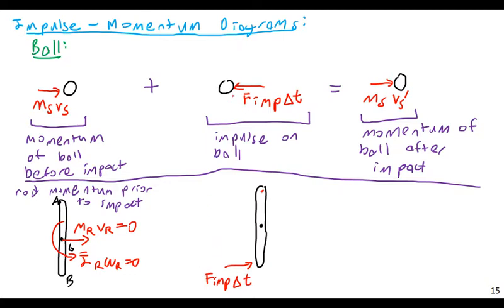Now, it doesn't matter which way I set these up, at least in the sense that I can make this one go to the right and this one go to the left, but it is very important that when you're setting up these diagrams for systems of objects, or for systems of rigid bodies, that you use compatible forces. You must set up your diagrams with compatible forces. Just put that in your notes. It is very important to set up diagrams with compatible forces. If you don't, you're going to get something wrong.